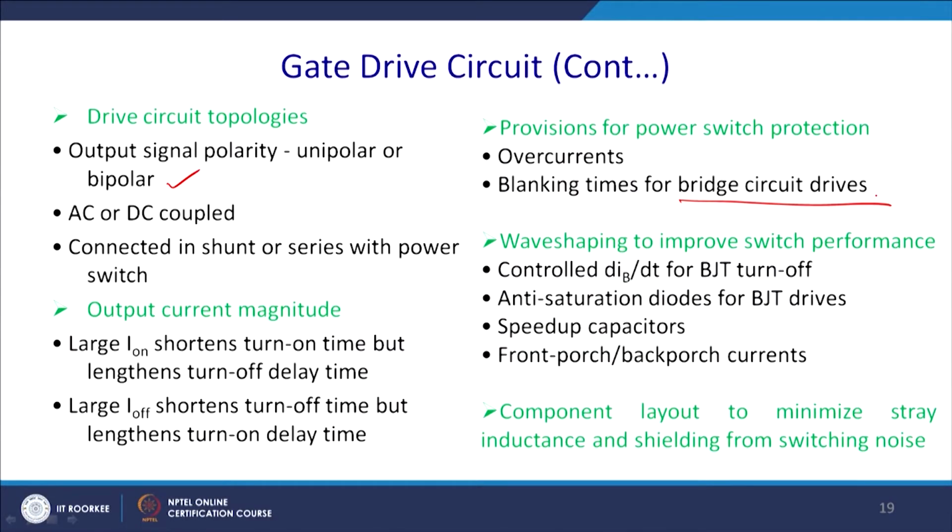Output current magnitude: large on-current shortens turn-on time but lengthens the turn-off delay time. This is one of the requirements. Large off-current shortens turn-off time but lengthens the turn-on delay. These are contradictory features, and we have to optimize them while designing.